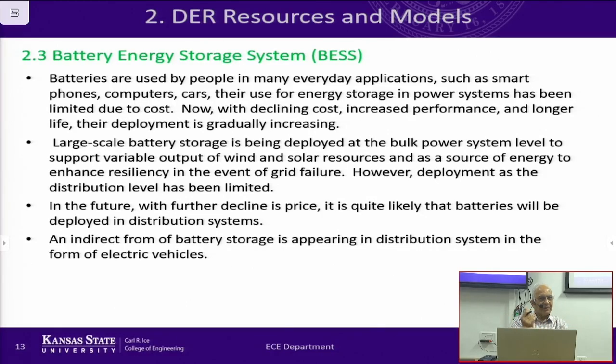So the problem is that if you put in solar panels, the cost of demand is not going to be impacted, because in the middle of the day your demand is already low, so you are not getting any benefit. But if you couple that with a battery, then you store energy during the middle of the day, and then you offset your usage in the evening as well as in the morning, and that system becomes more economically viable. So sometimes batteries can actually help.